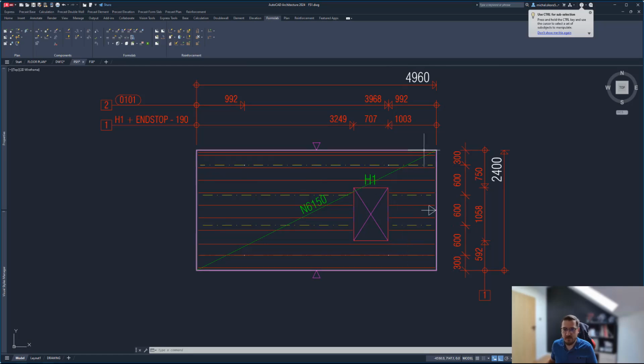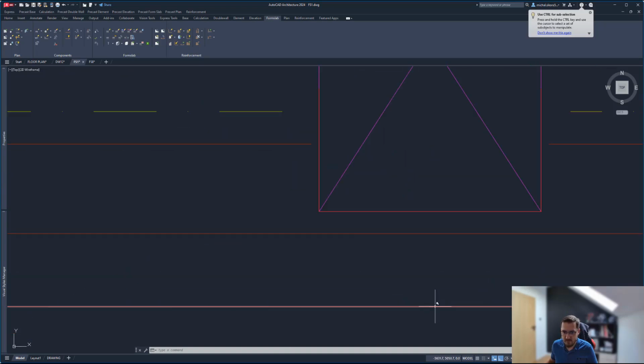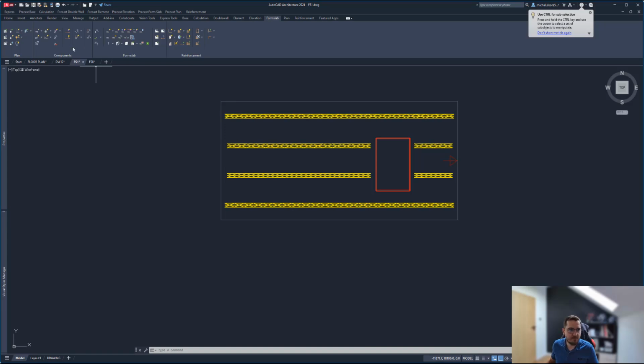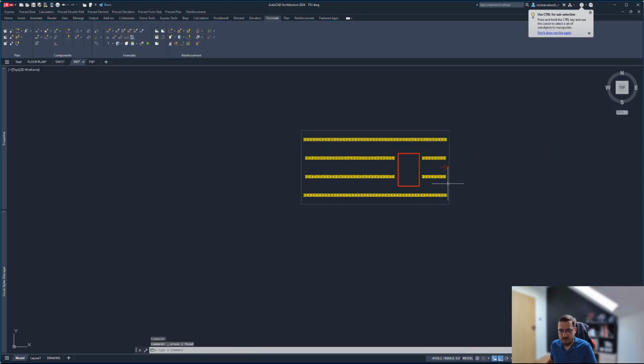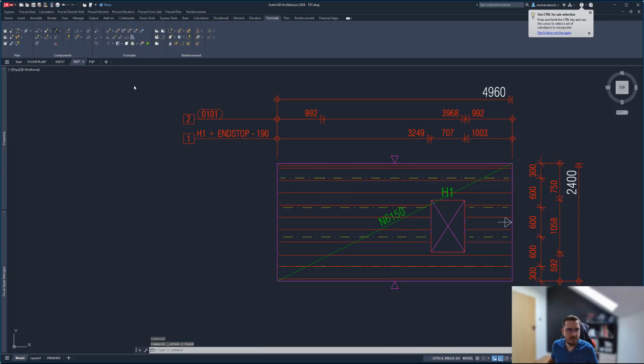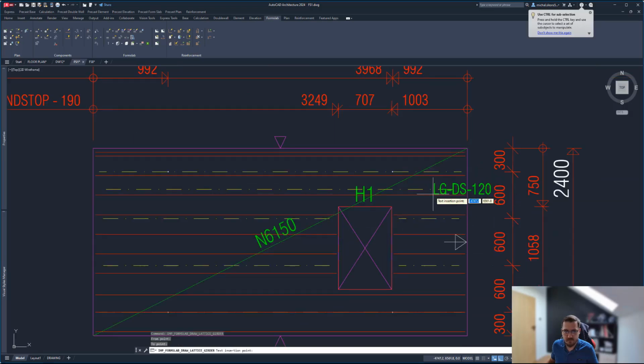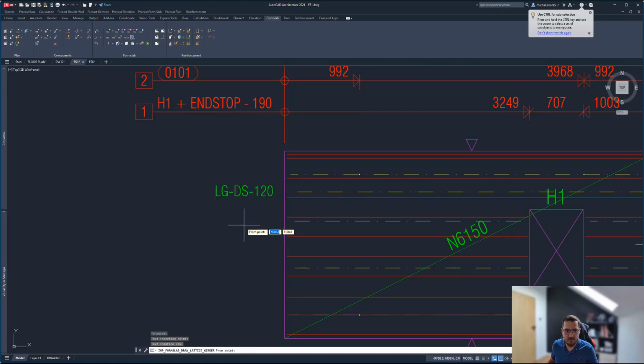So you have the girders here, basically some additional reinforcement, red reinforcement, yellow girders. Girders are cut here, maybe warrants moving reinforcement a bit, and we have those girders as well. Now, if need be, of course, we can, for example, draw a lattice girder, and we can specify the type of lattice girder that is. Let's maybe do this one. And we can specify that from here to here. Maybe let's not do that in the 3D view, but let's do that in the 2D view. And we can add that girder here and maybe add the description of it here.